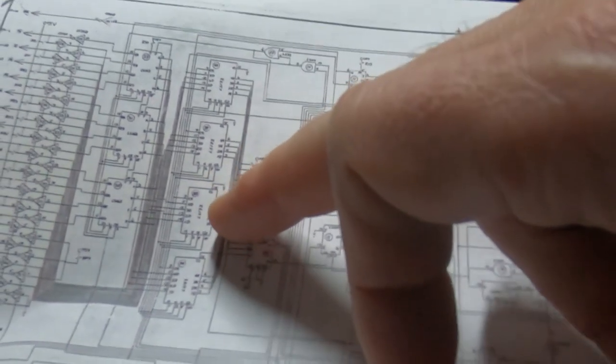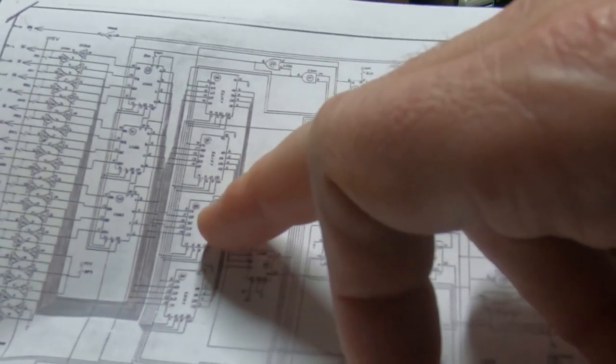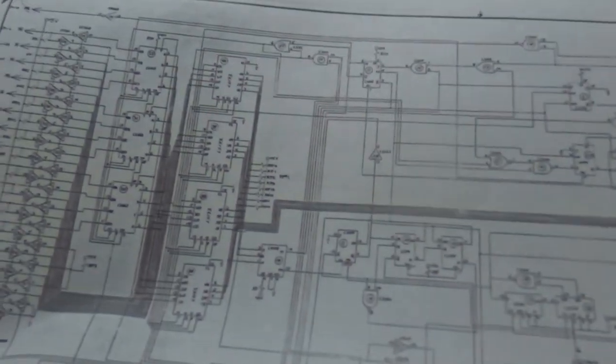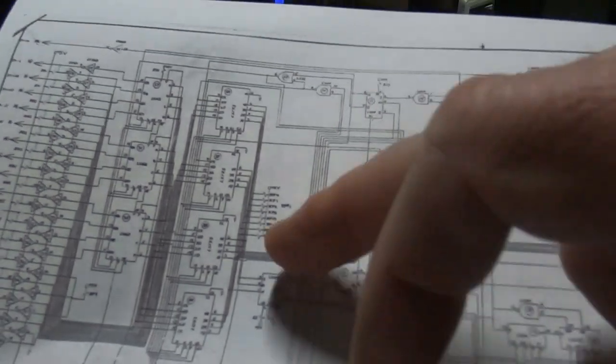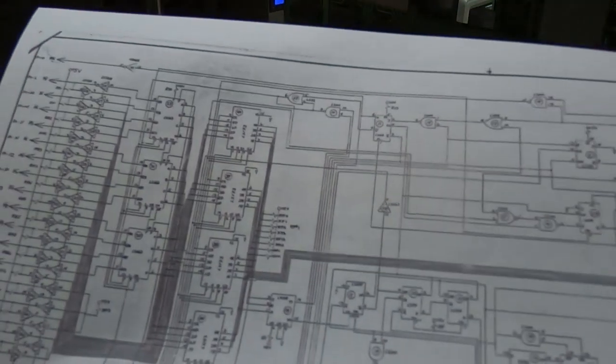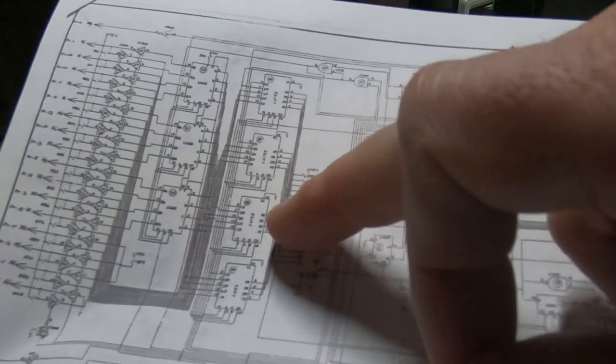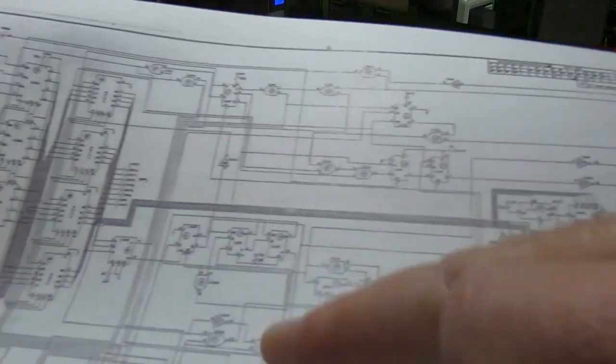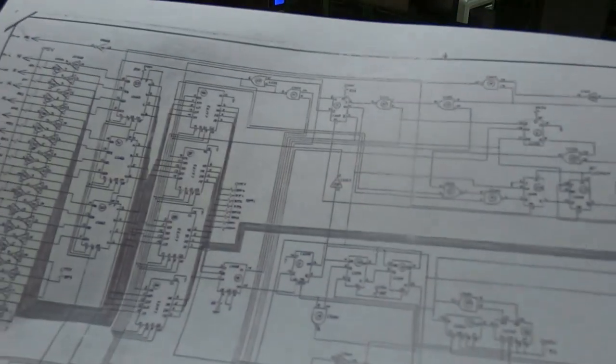We could try the techniques. We could attach the logic analyzer, check the input and output based on when they're being latched and see if they match. But the easiest solution is, as I say, just to piggyback another device. So we'll start off with this one. It might not be this one, it could be one of the others, or it may be something else, but I suspect this is the device that is the culprit.